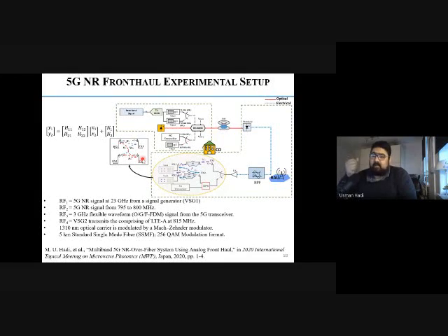And then another question can be why the VSG2, which is signal generator 2, is giving a window of 795 to 800 megahertz. Why are you not using a fixed value? So we will see why we are trying to mimic from 795 to 800, because the other LTE advanced signal that we are using at RF4 is 815.